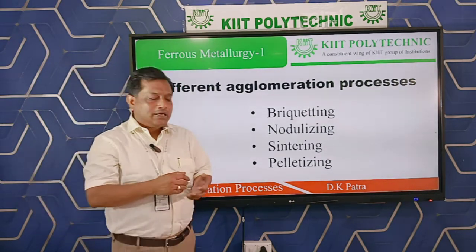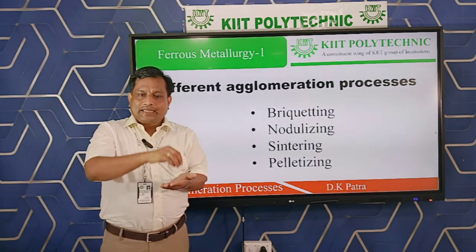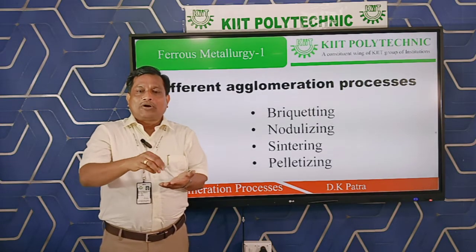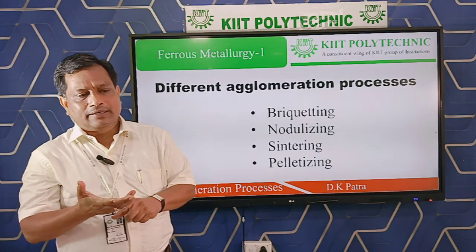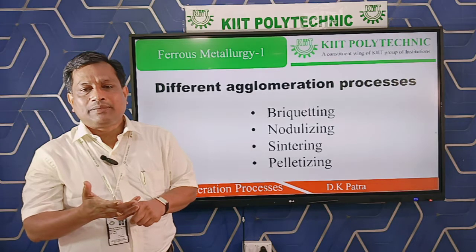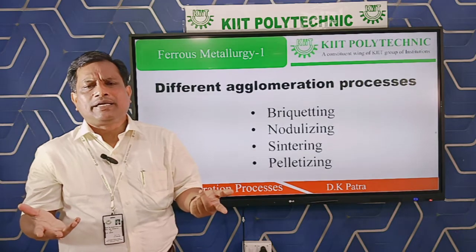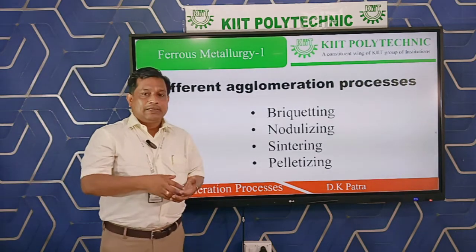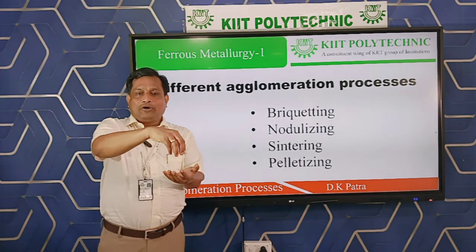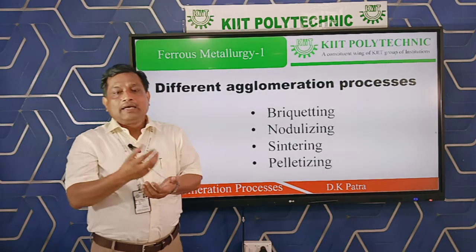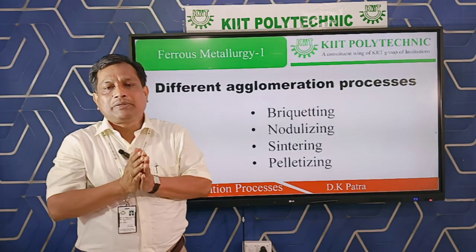How are we making it? Here we take small particles. We crush the iron ore collected from the mines. Those crushed particles are put in a block along with moisture as well as a binder. As binder, we can use bentonite, lime, tar, sodium silicate, magnesium chloride, whatever binders you prefer. With the help of the binder and the moisture, the mixture is put in a small block and pressed, and then taken out, because the particles are now attached to each other by the help of the binder and moisture.